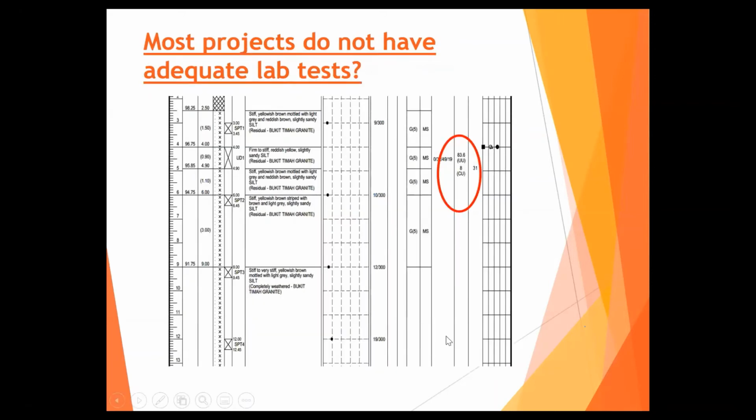Then you see the whole bore hole here, about a stretch of 13 meters. They only do one lab test, and most projects are not research projects, so everybody is looking at money only. So they will not have a lot of laboratory tests to test whether it's really a predominantly clay or what sort of soil. That is a real fact that you're looking at. That's why this is called practical geotechnical guide. It's not according to I want to test every sample. You do not have the luxury in the actual case.